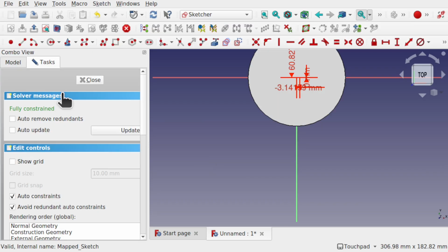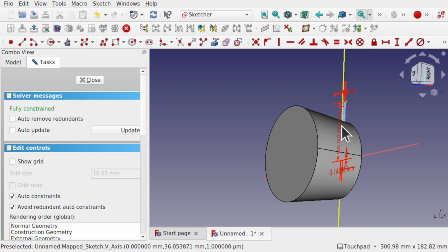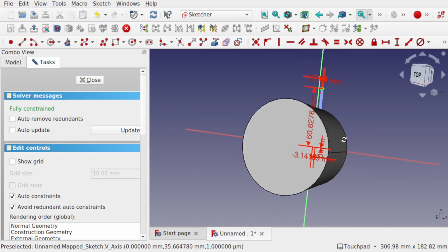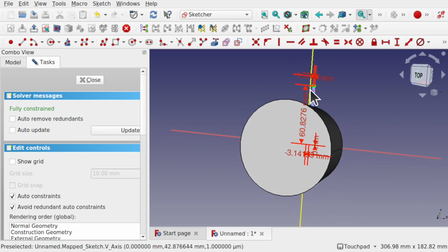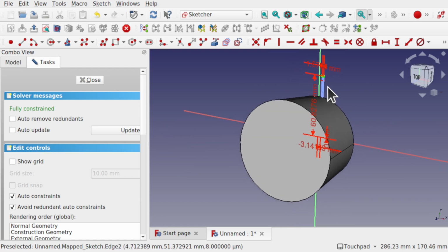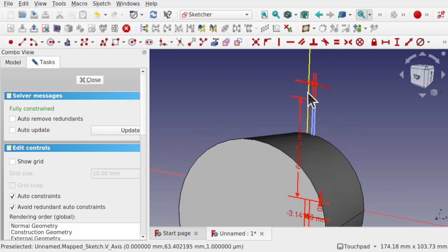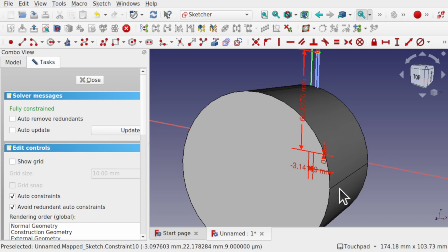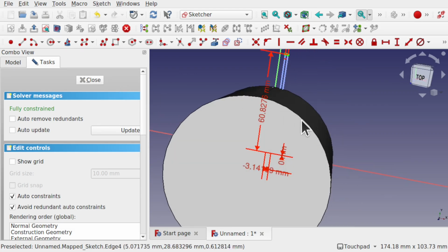Now if I double click on that map sketch, what we'll normally get is a rectangle that's unraveled this surface flat. But this won't unravel to a rectangle. So we'll get this sliver sitting here. So we need to transfer the longest edge from the top or the bottom, depending on which one's the longest edge, to our measurement here. We've got the correct measurement going down this way, so you can see that there, but we haven't got either the top and bottom. So we need a length from this edge.